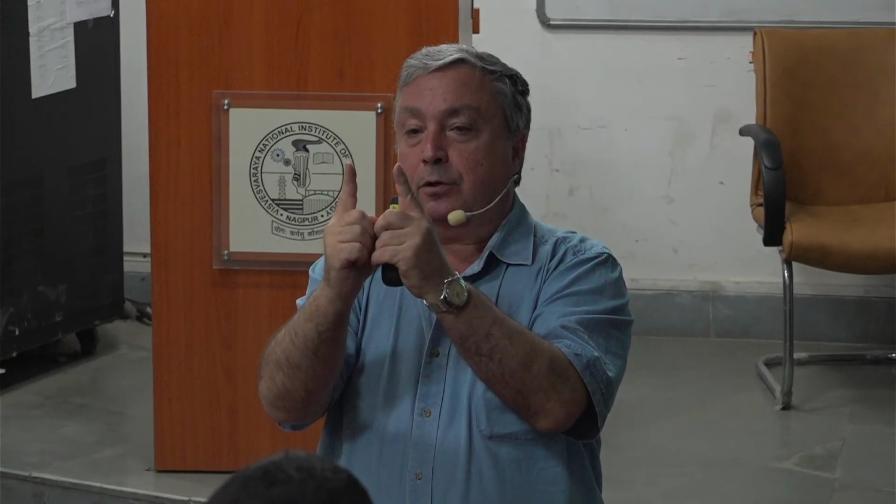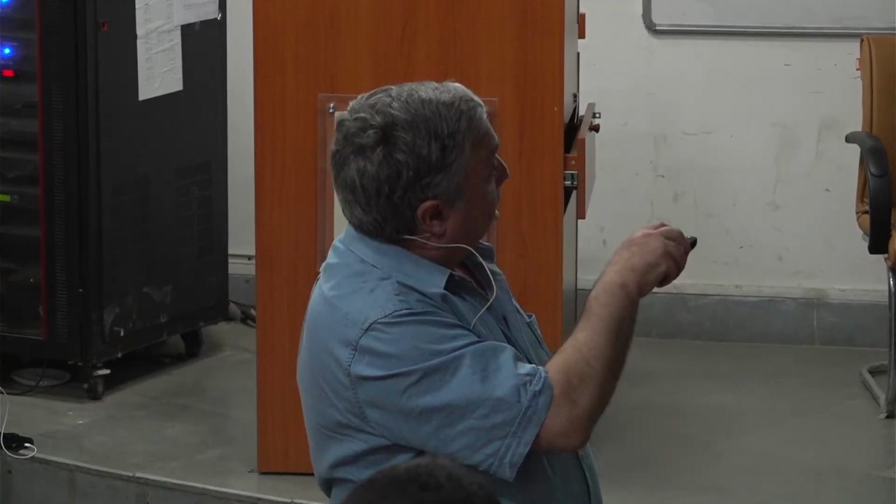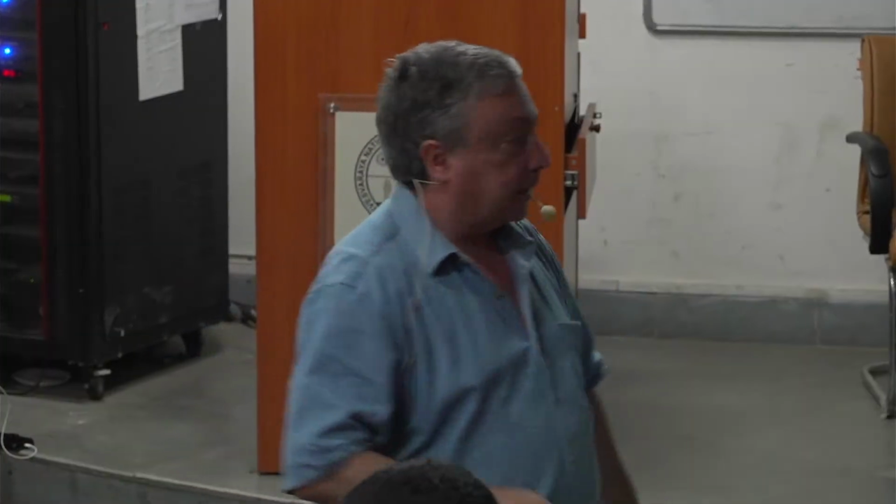If you have 400 milliamps passing here, and this opens in a few microseconds, you go from 400 milliamps to 0 milliamps, and behind you have a huge inductance that will respond with a voltage pulse that can go up to several thousand volts. These several thousand volts will be across the electrodes, and your plasma can strike.